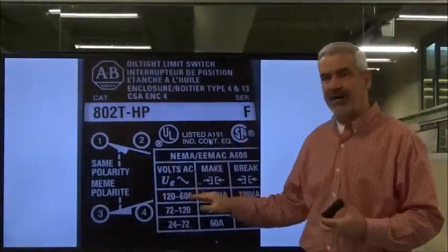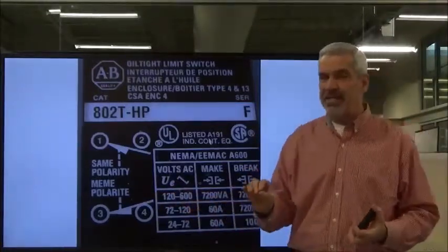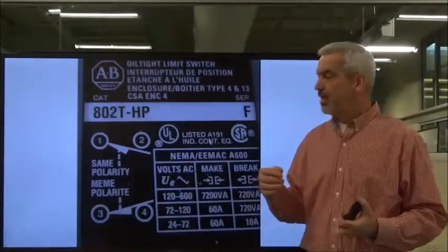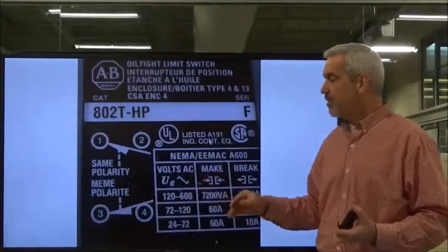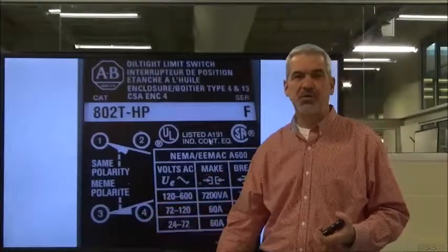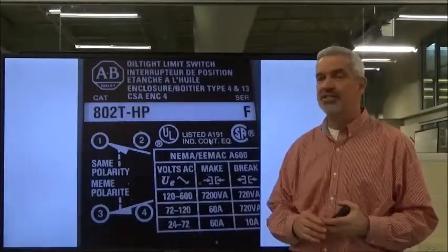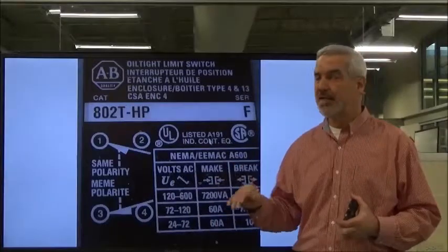You will never have these in a three-phase motor circuit. Now, you may have these in light residential or light commercial motor circuits, where they actually turn the motor on and off, and those contacts will be rated for those small motors. But we're talking about industrial three-phase induction motors. You will not see those in a power circuit. You'll see them in the control circuit, but not in the power circuit.